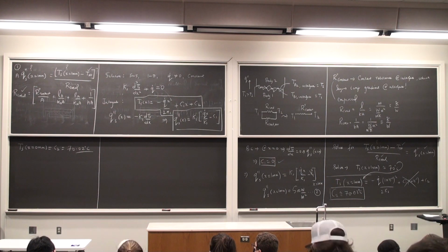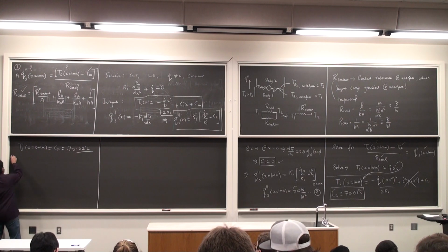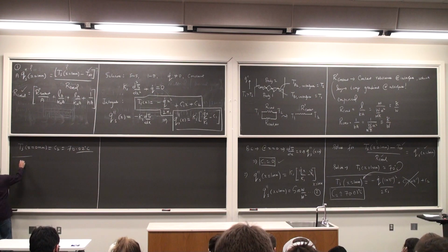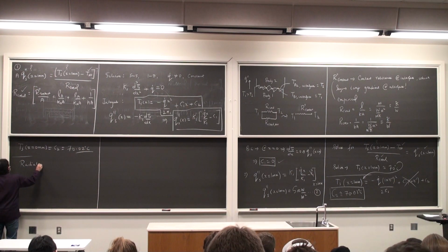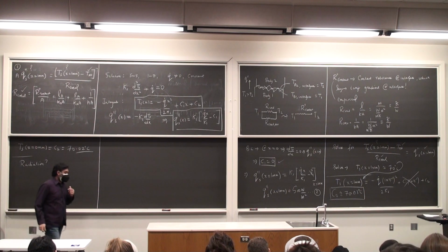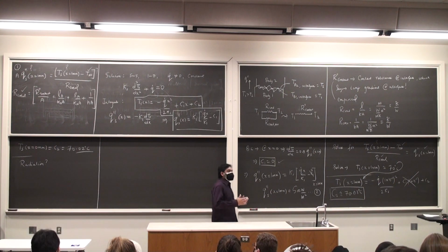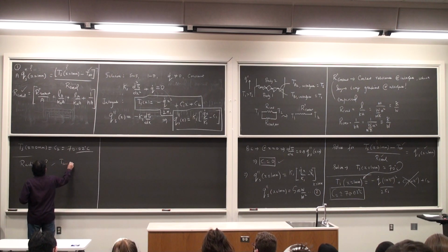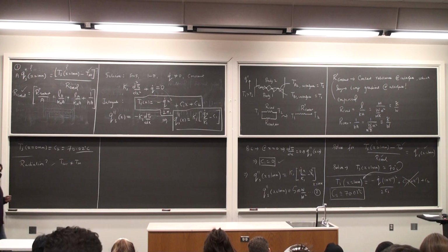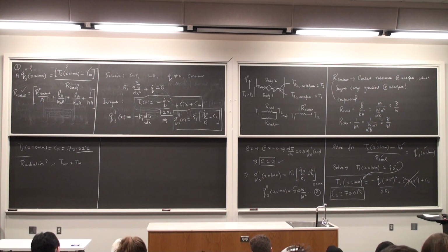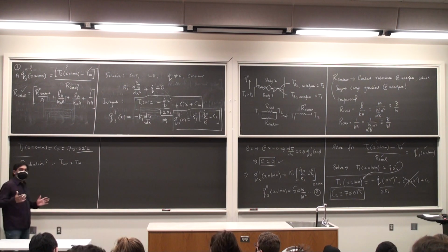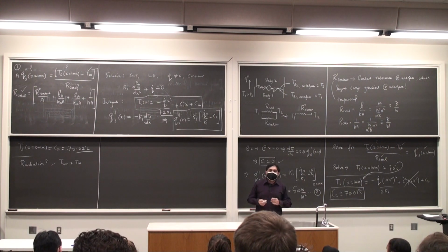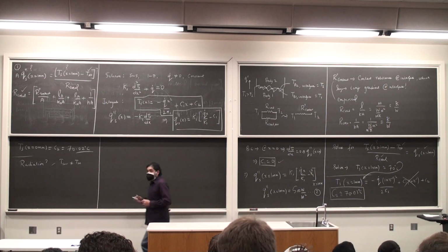Now let me bring in our good friend radiation. So what happens if radiation is a factor? Okay. Let's see what happens. Two options here. One is the temperature of the surrounding is different from that of the surface, ambient. So here I could have the surrounding not the same as T infinity. Typical situation is when you look at an engine block that gets really hot due to the combustion reactions. The temperature there is really much higher than the ambient air around. So that's where radiation becomes significant.